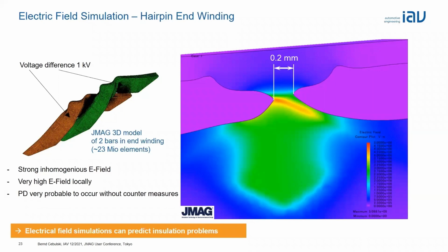So you might think that this is a quite easy simulation, but I can tell you it's not. Not only because it's 3D, the biggest problem is that the mesh refinement does not have to be in the material. You need the mesh refinement in the air, since everything related to electrical field strength is looking at the air region and not at the materials, because in the material the electric field strength is constant. So you need a very specific meshing model here to make this simulation converge.